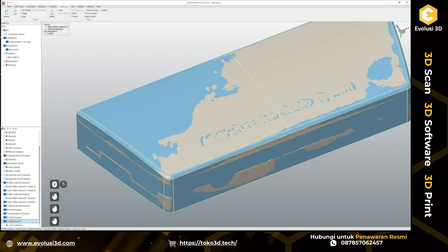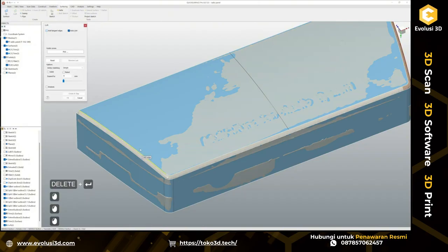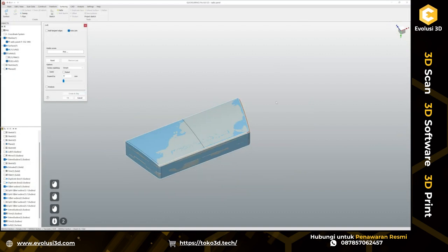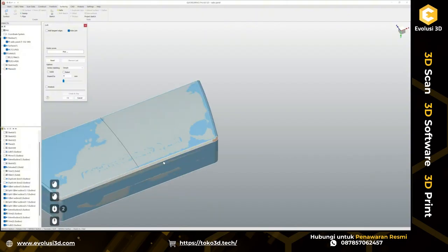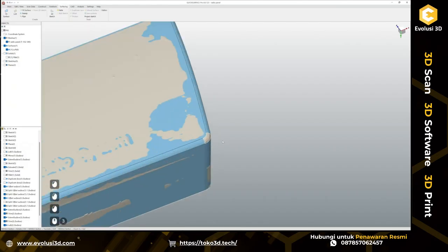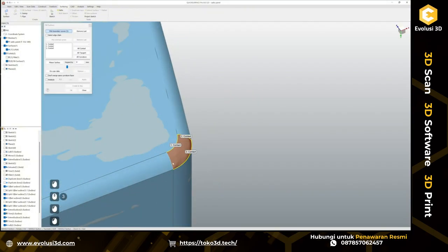And in order to recreate them, I can go and simply create here several lofts like this, like this, like this. Okay, and we can now go to not loft, but to the fill surface tool. Select all of those edges, set here tangent, tangent, there we need a contact.